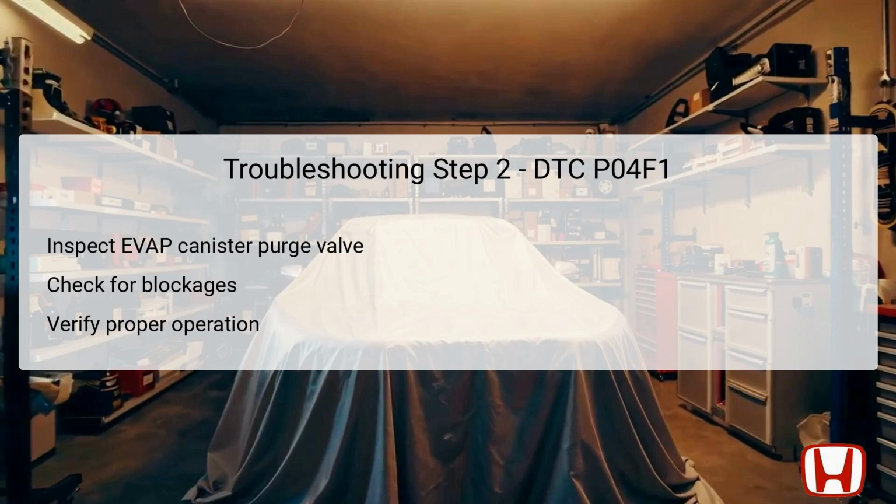Verify the valve's operational integrity by conducting a functional test as per the specifications outlined in the diagnostic manual. Any abnormalities in its operation, such as leaks or sticking, indicate that this component is likely the culprit for low purge flow. A thorough check of the valve ensures that there are no interruptions in the emissions control system.